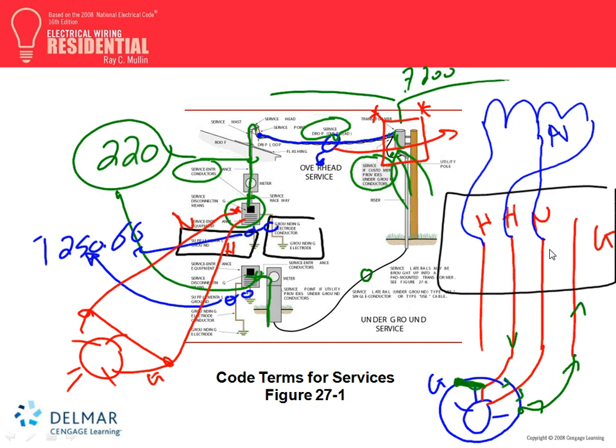You have a point. This is grounded at the transformer. This is grounded, and I am grounded right here. I have my ground, and these are connected through Mother Earth. You're right. So the ground fault current can go directly through Mother Earth, and could trip the circuit breaker, completely right, except it's not fast enough to make it trip, guys.